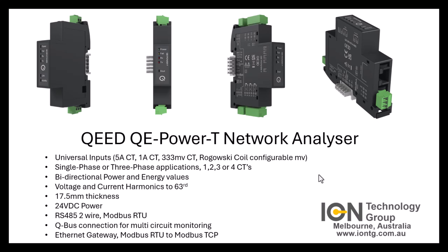If you prefer to use Modbus TCP connection, there is a gateway which supports Modbus TCP and also QBus, so you can have Ethernet Modbus TCP, data going to SCADA, RTUs, etc. connected to multiple meters via QBus. So let's have a look at configuring this device.